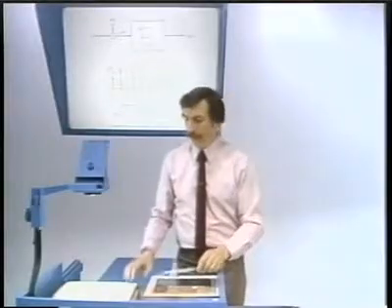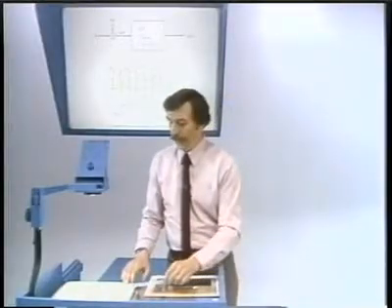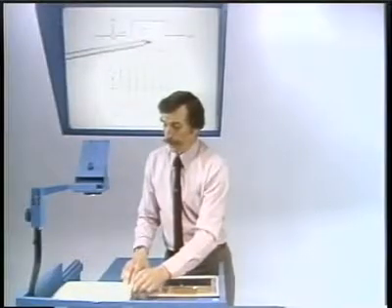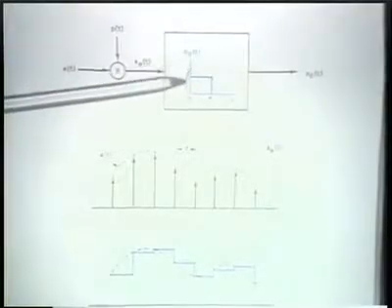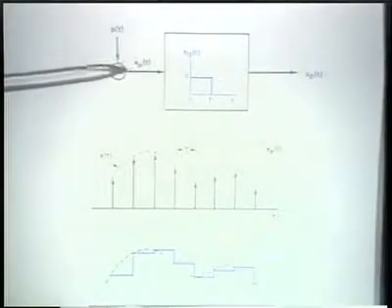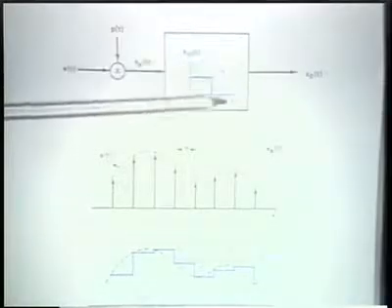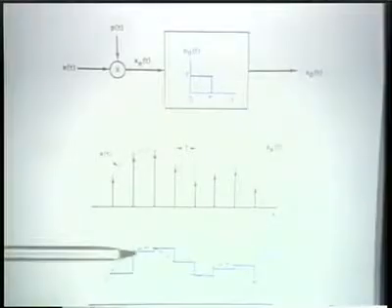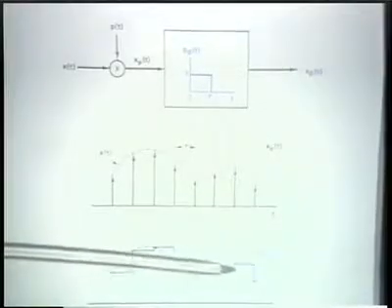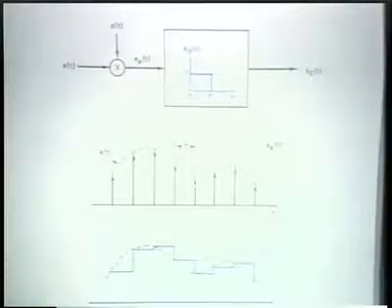Specifically, if we consider a system where the impulse response is a rectangular function, then exactly the reconstruction that we would get by processing the train of samples through a filter with this impulse response is what I've shown here.